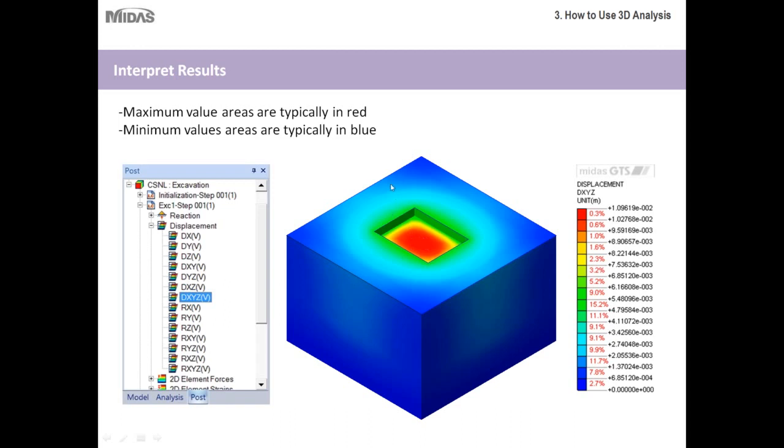As you go further and further away from the excavation site, the displacement becomes less, up to the point where it's almost negligible. And that's what I was talking about with boundary conditions. For example, if I were to make my model too small, if I made the edge along here, then there'd be strain going past that point that I would want to account for, so I would want to make my model bigger. As you can see, the model is big enough, so all the strains and displacements are within that range.